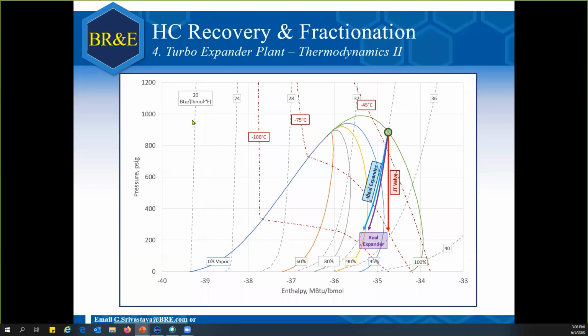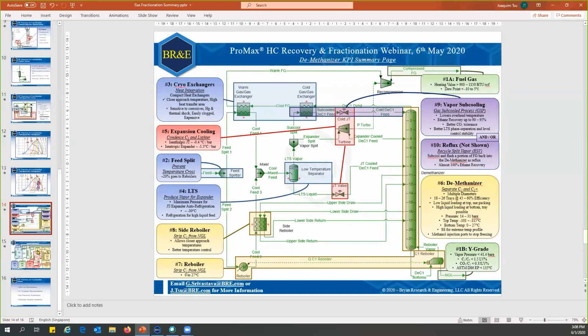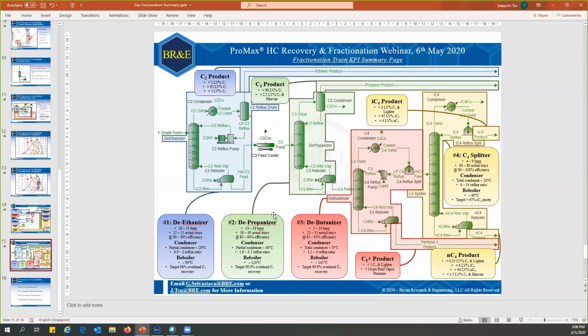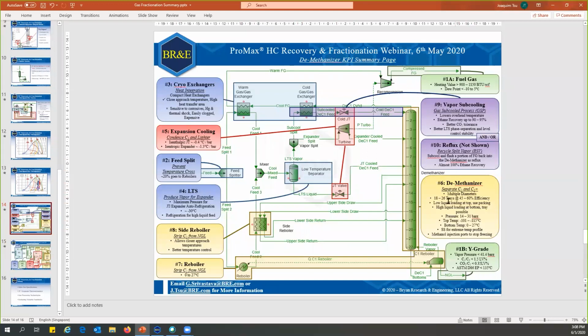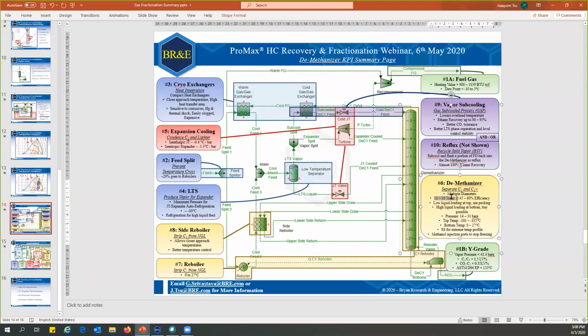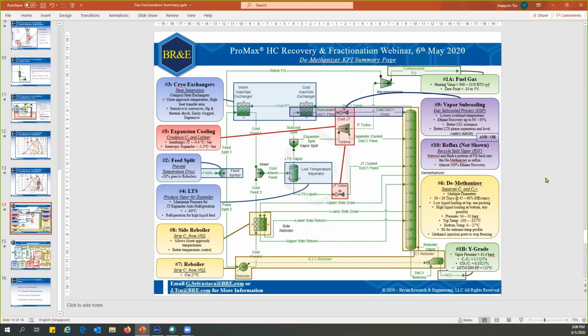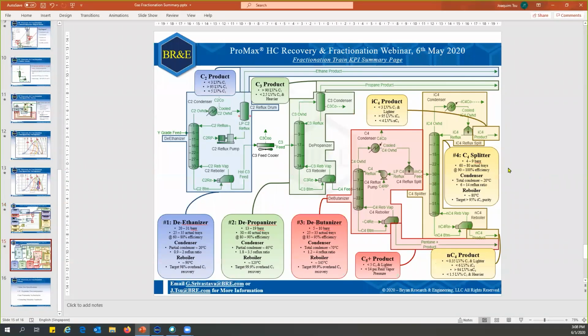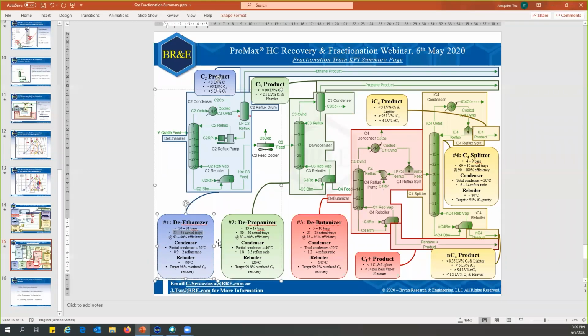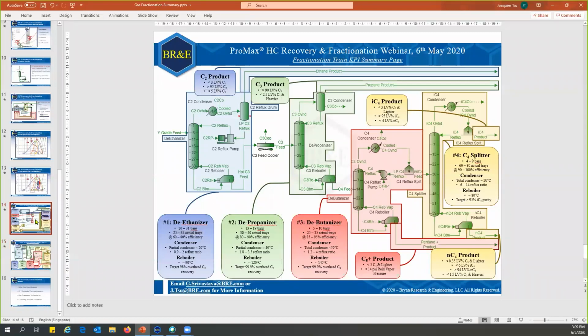Okay, I have some questions about the different layouts and stuff. So again, I'm going to send all these files out. But for example, if you look at the demethanizer, I've stated over here we have 18 to 26 trays at about 45 to 60% efficiency. And as for the different splitters, all of their trays and efficiencies are listed down over here. So when we send these out as a PDF, this will be a very good reference for you to pick and model what you want.